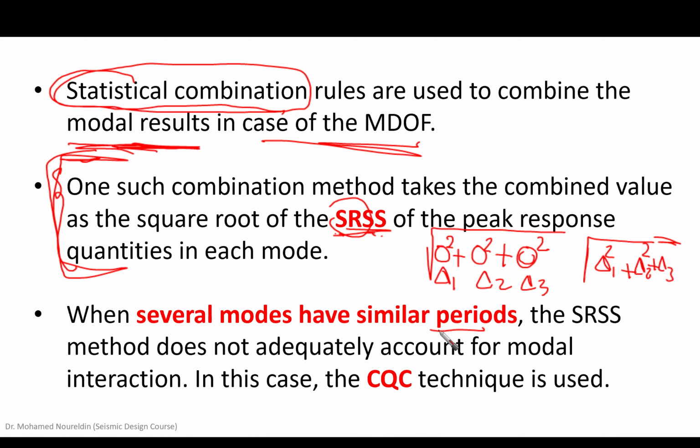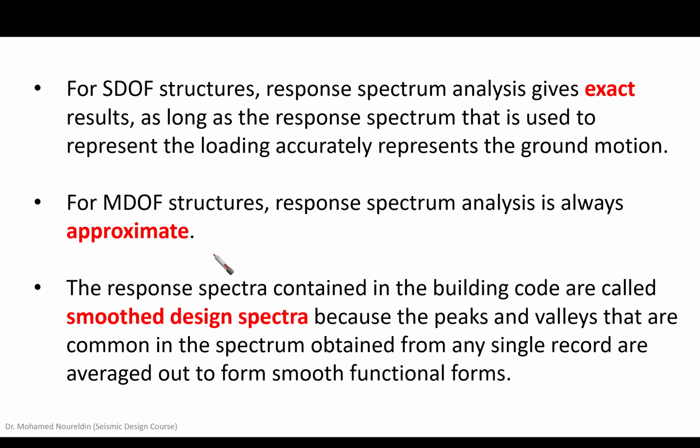Whenever we have similar periods, the SRSS method does not adequately account for modal interaction. In this case, we use another combination. We call it CQC, complete quadratic combination. You can find this in the dynamic analysis course also. Now let's go to the next part.